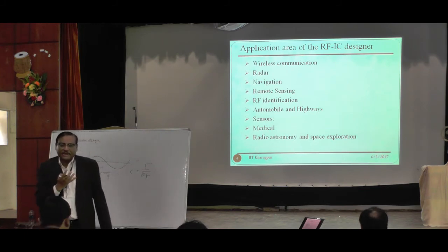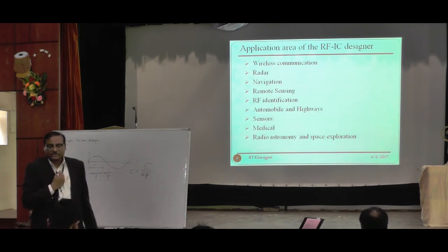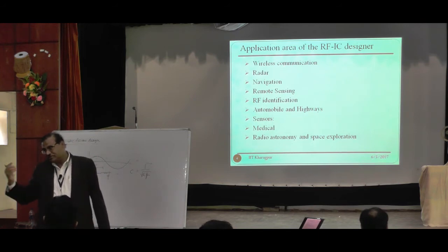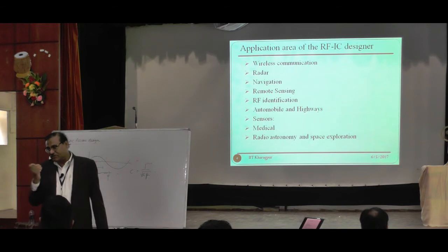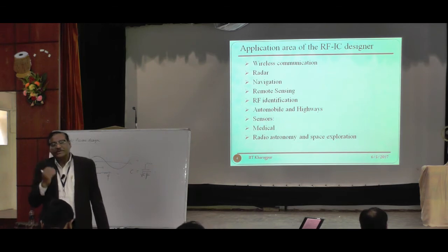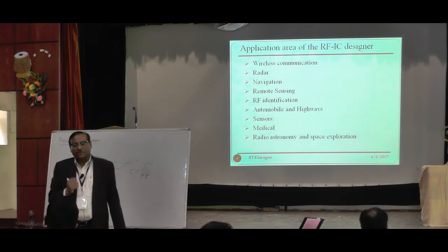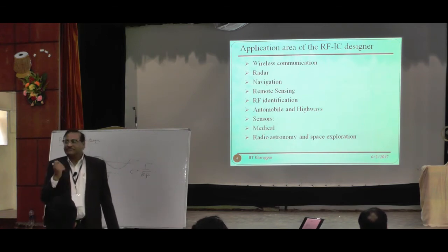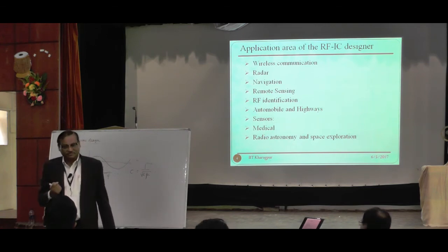That is the point at 10 gigahertz where I will be concerned that my lumped parameter model is going to fail. Why? Because of the wavelength, phase distribution, and component size, you will have an appreciable phase difference. So that point I have to look into. But look here, 0.3 millimeter, and what is the device size?